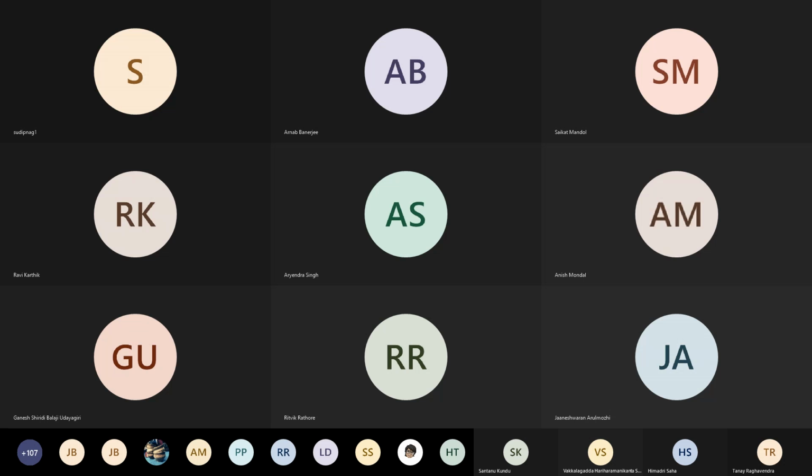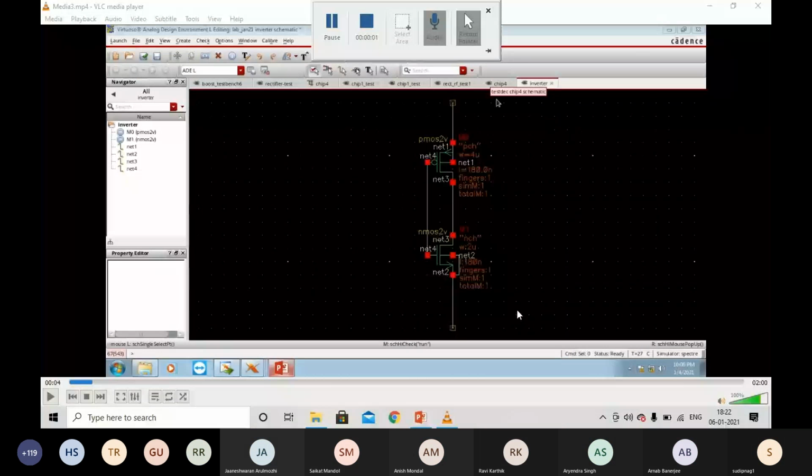Suppose you are designing a very large circuit which requires, let's say, hundreds of inverters. How are you going to draw such a large schematic? It is not recommended to draw 200 transistors and show all the connections in between. If you look at this CMOS inverter, there are 4 connections in this basic form, along with 2 transistors. So there are 4 wires and 2 transistors. If there are 100 inverters, there will be 200 transistors, and 4 into 100, that is 400 wires, should be drawn manually.